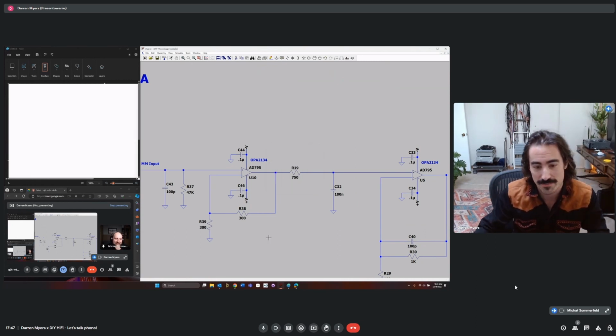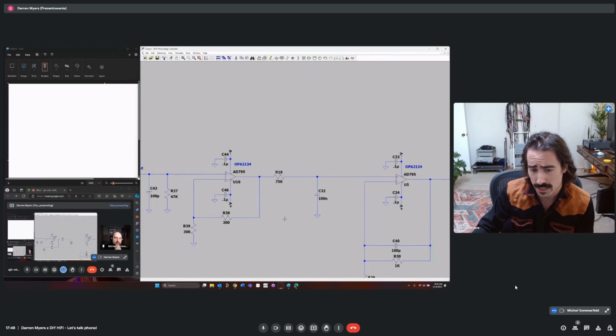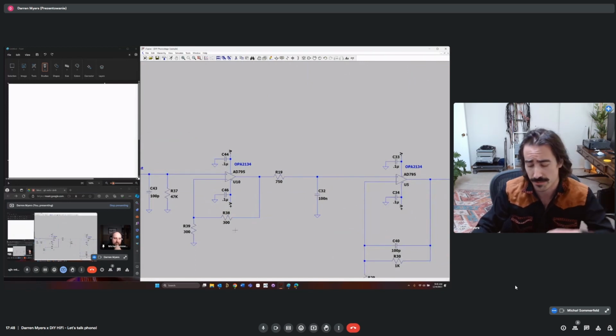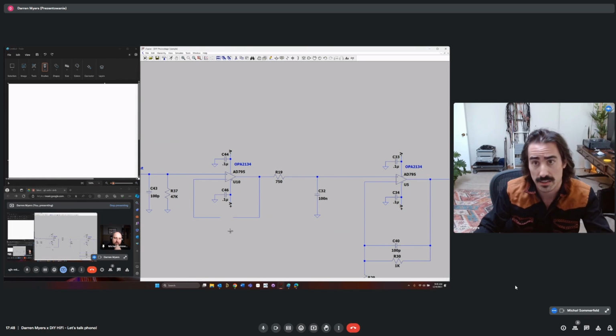But you see, this is going to give us 6 dB, but now the amplifier has to drive R38. And so that's problematic from a perspective of just loading this down too much. So for that reason, I'm actually much more of a fan of your idea of paralleling the buffers, which you can do.